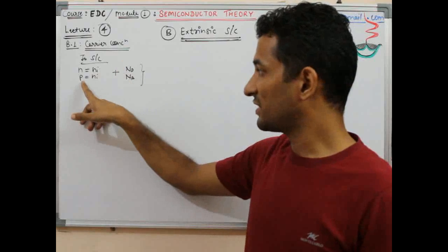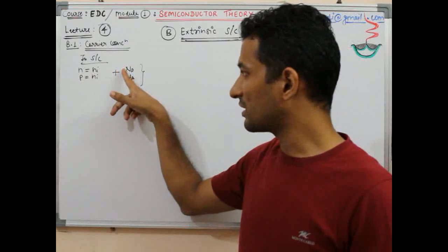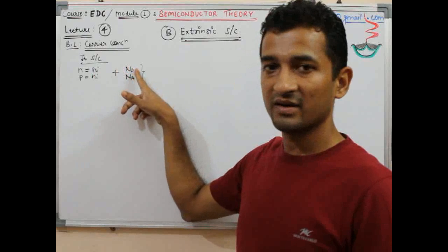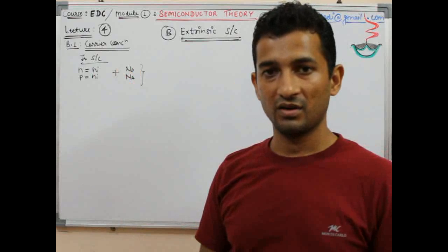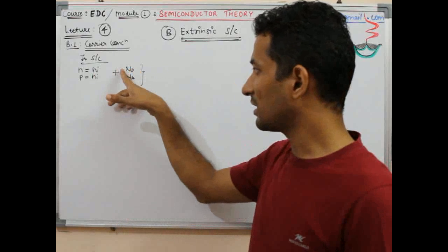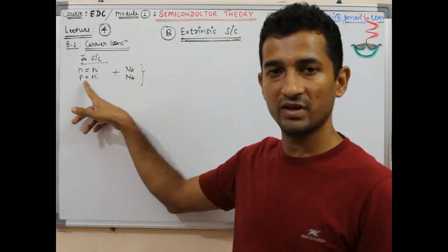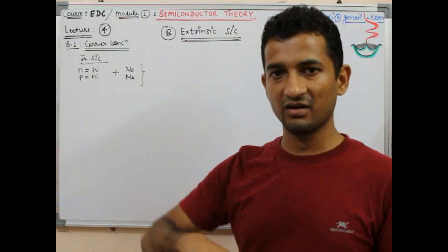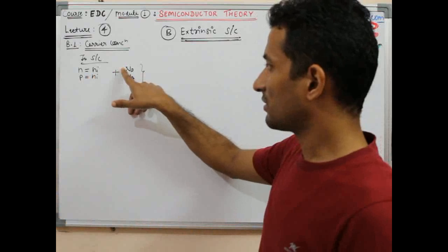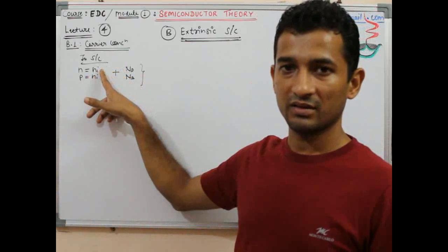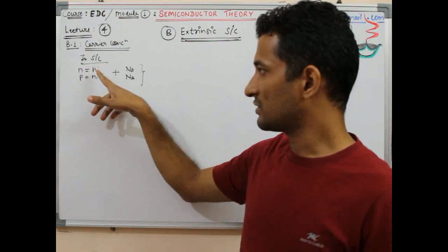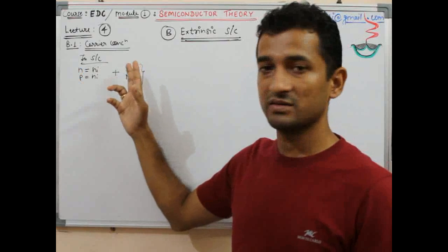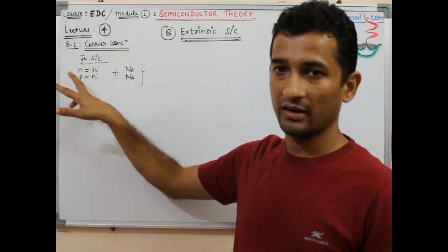So in order to compensate the 10 to the power 10 holes, only 10 to the power 10 electrons are recombined, or compensated. What remains after that is still 10 to the power 14 or 15, because we are taking only 10 to the power 10 electrons to recombine with them. So almost all the externally inserted electrons are still left. Then they all add up with Ni, or with N. So N plus Nd is approximately Nd, because Nd is still 4 or 5 orders more than this N.